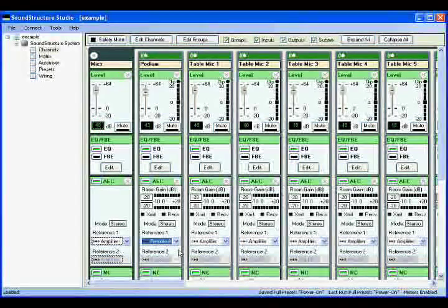If the echo canceller reference for the table microphones was changed to be the remote audio submix, then when the podium microphone is reinforced into the room, that audio will be treated as a local talker, and if it's loud enough to activate other microphones in the room, then those microphones will transmit that audio to the remote side as well. These multiple copies of the podium microphone audio will cause the podium microphone to sound more reverberant to the remote participants than if we left the AEC reference for the table microphones to be the amplifier channel.